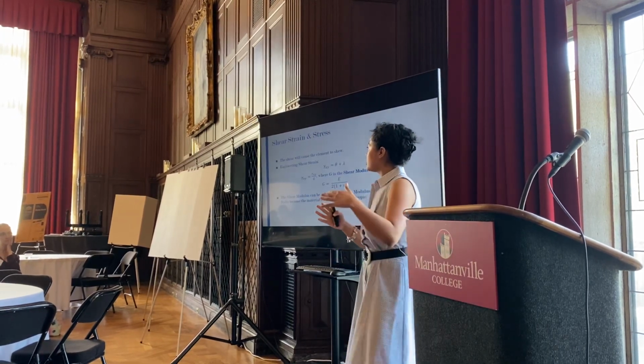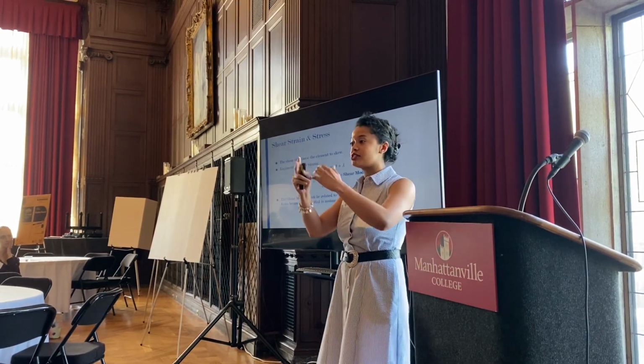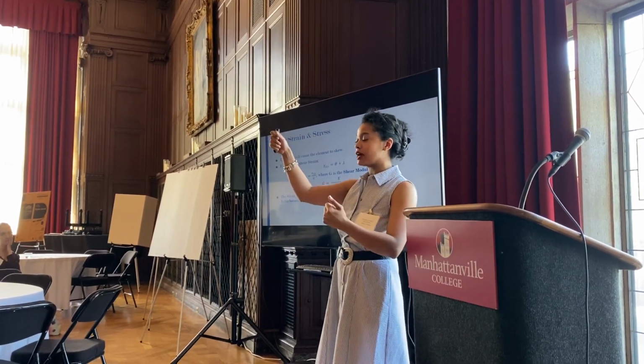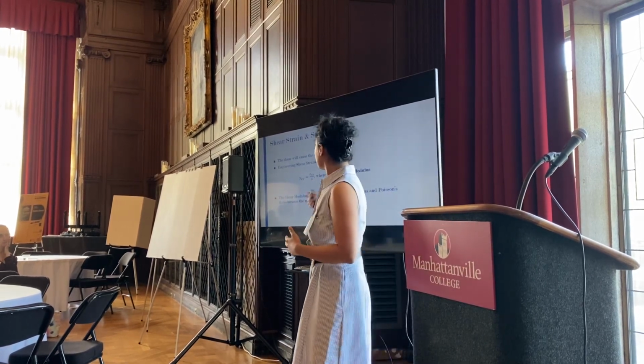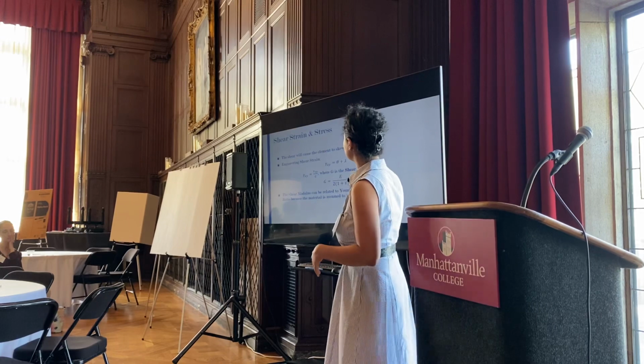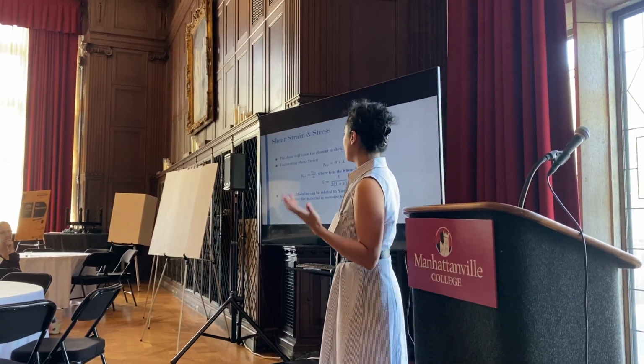Skewing is essentially when you have two shear stresses that are perpendicular to each other and they intersect, and then it'll pull in a diagonal direction, causing an angular displacement, as you saw in the previous slide. These angular displacements can be summed to get our engineering shear strain, which is gamma sub xy in this example.